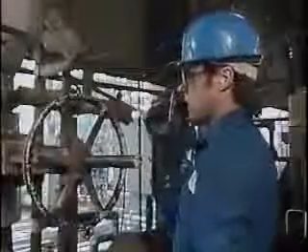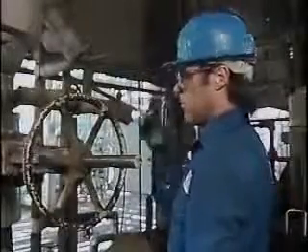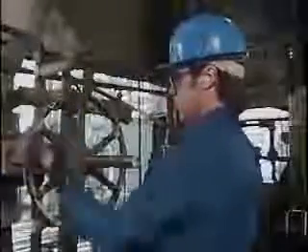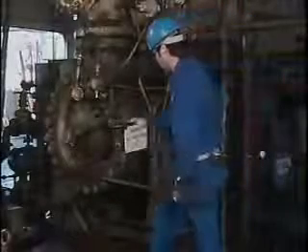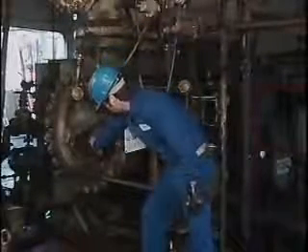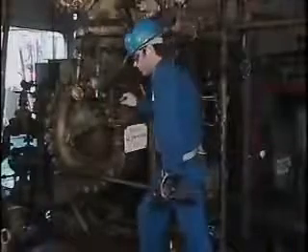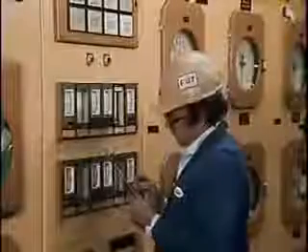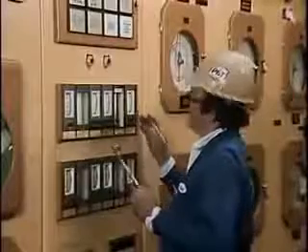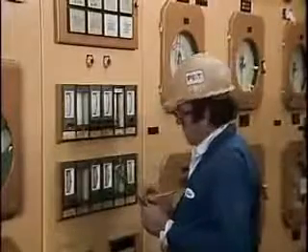Now, when a compressor is shut down under normal circumstances, the compressor is allowed to gradually slow down and cool off. It's just as important to monitor a compressor during shutdown as it is during startup. Checking for unusual sounds and vibration can help operators identify problems so that they can be quickly corrected. Keeping an eye on instrument readings is also important because they can tell you when problems are developing.